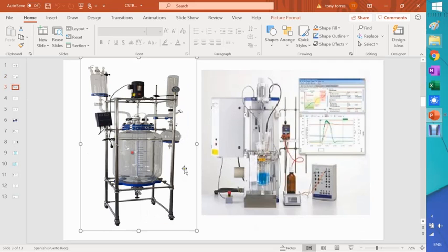But before getting here, it's good to have a very good idea of what your reaction will be doing, right? Whether they have an exotherm, or whether they will kick in an exotherm that you're not aware of, which is the problem when you are not aware. Because when you know that there's going to be a huge amount of heat produced, then you are prepared with the proper jacket sizing and everything, just to reduce the temperature, just in case. But you need to know first.